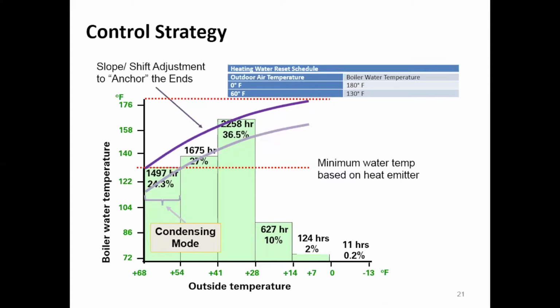And from an efficiency standpoint, if I go to the far left-hand side, I'm sitting at probably about 112 degrees Fahrenheit, which is probably somewhere a little bit more than 92% efficient, maybe 92 in that range. So the highest the efficiency becomes is 92%, and it's for a small fraction of the heating season. All of a sudden, in this application, it becomes very difficult to budge above the 90% number for the seasonal efficiency of the boiler. Now, with the heat emitter, this purple curve really is not a good representation of its response to a change in water temperature.